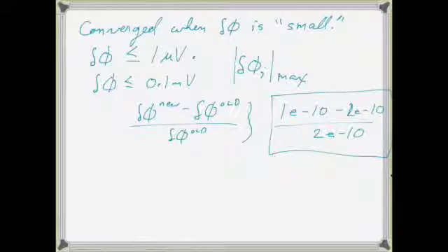So this is Newton-Raphson. This is how it works. This is the algorithm. This is how we calculate the Jacobian. And it's just been the real workhorse of our NEGF-Poisson solvers. And it's the fastest scheme we have. But there is one that seems to be slightly more robust, and that is the Broyden-Anderson scheme. So that's sort of the end of Newton-Raphson.